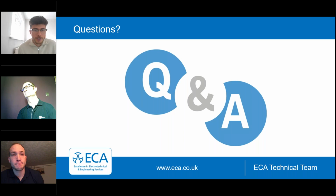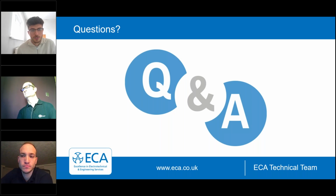Well, yeah, if your incoming impedance is high at origin, it's obviously going to affect the results that you obtain within your system. So if your network or your supply earth is poor, then that's going to affect all of your circuits, and could be a big issue within your installation and achieving disconnection for your circuits. Hopefully that covers that one. So yeah, the quality of your supply earth is important, because it's going to affect all of your circuits.